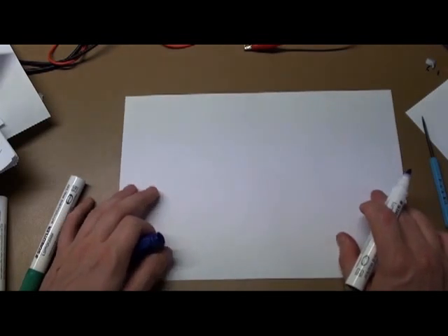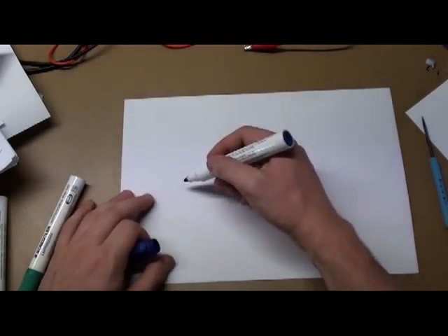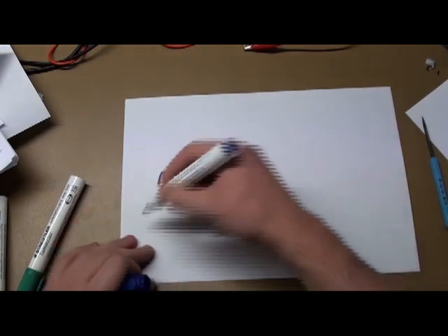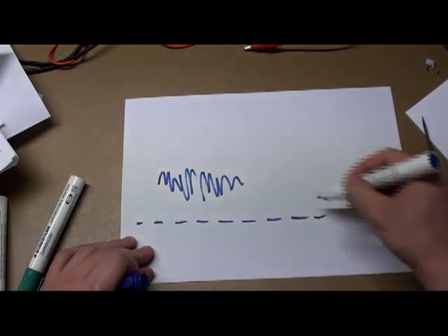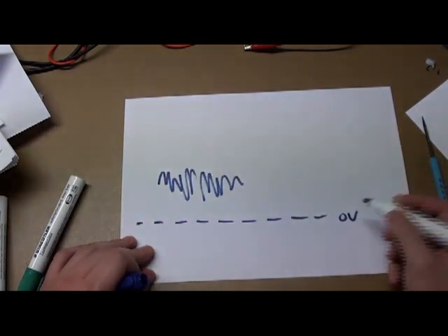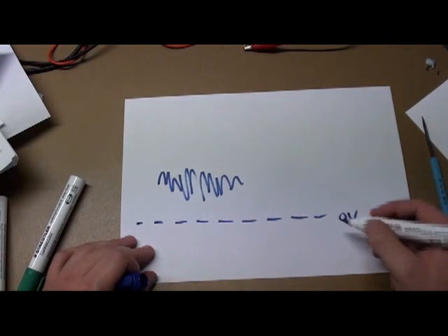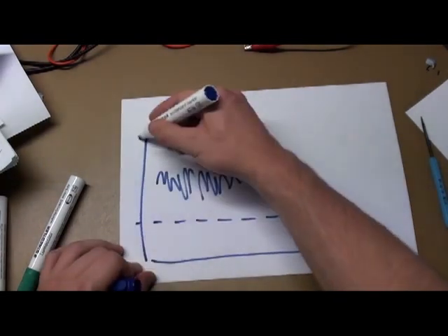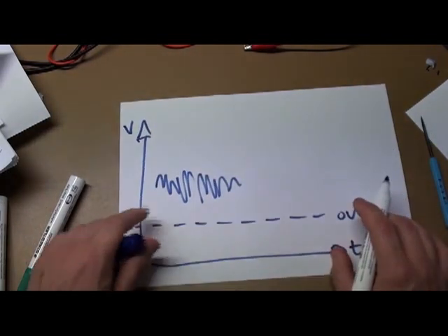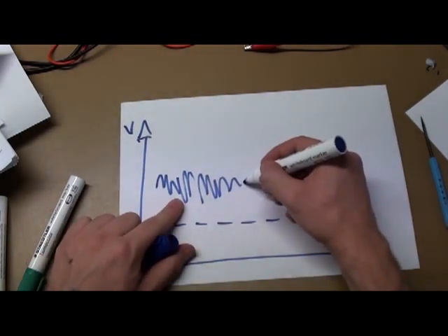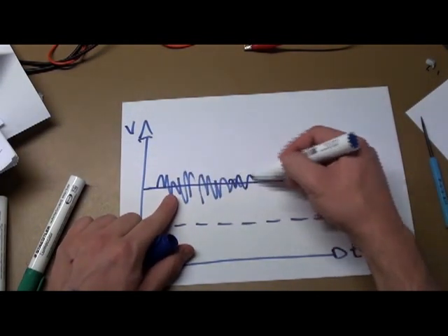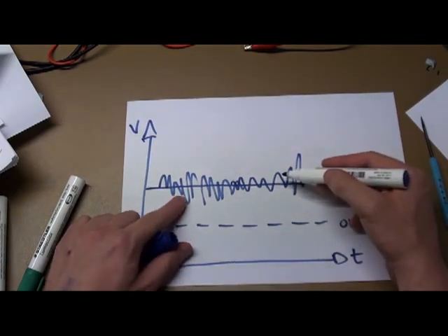So, back in terms of the strain gauge project, we might have a signal coming out of an instrumentation amp that's going like, and this would be 0 volts, and this would be time, volts. So really the value of strain we want is this value in the middle. We don't actually care about all this flipping and crazy stuff.